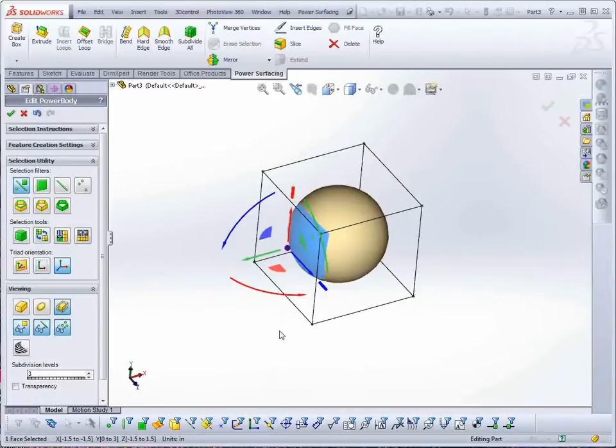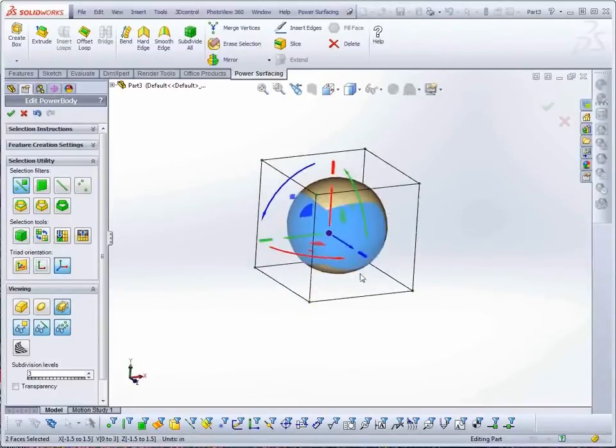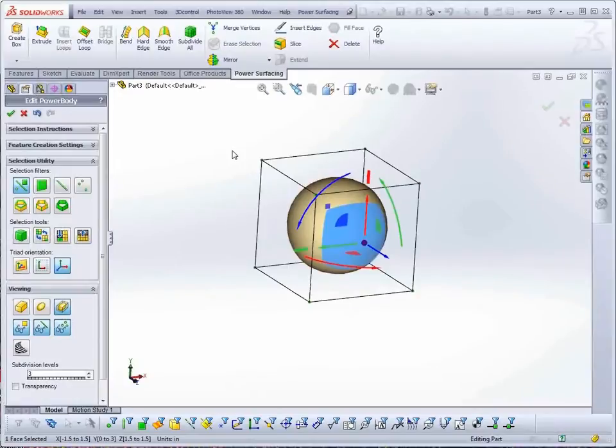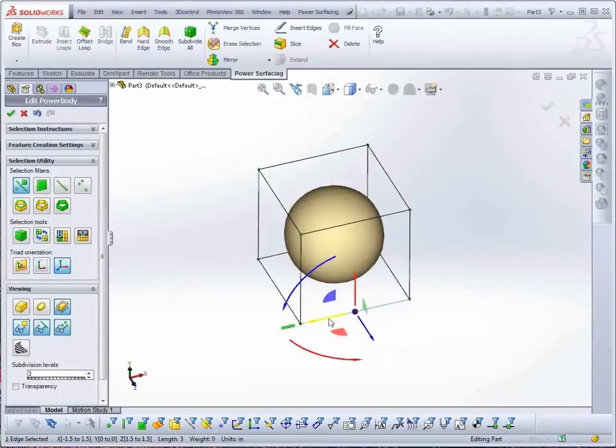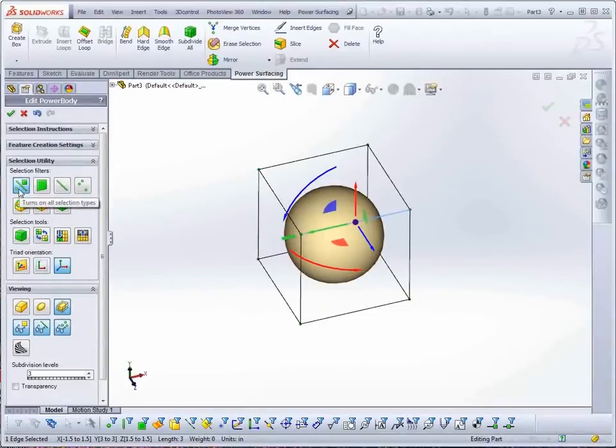You can hold the Shift key down and continue picking, or region select to add to the selection. Dragging from left to right selects Windowed, while dragging from right to left selects Crossing. Note that as soon as you select an element and hold down the Shift key, you will only be able to select more of the same type. To remove from the selection, hold the Control key and pick. Releasing the Shift or Control keys returns to the Select Any mode.